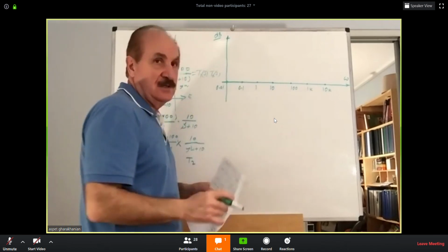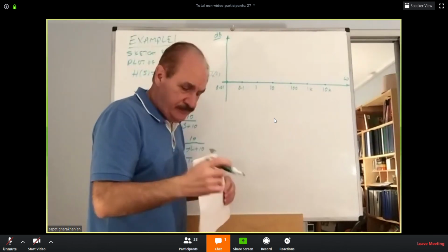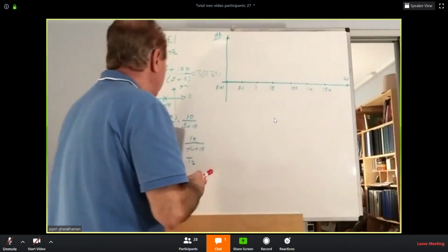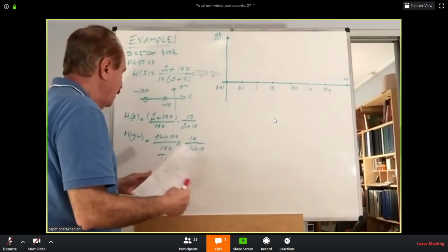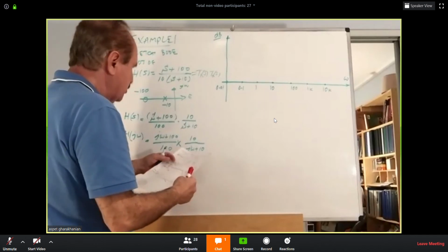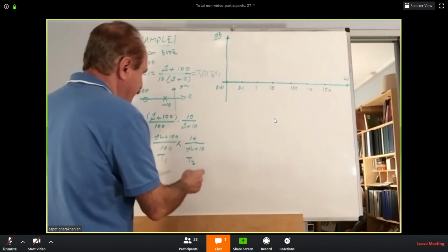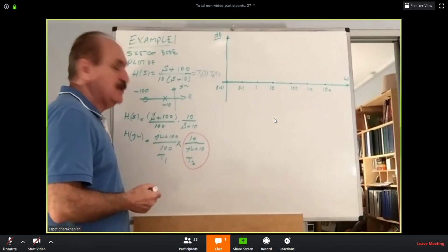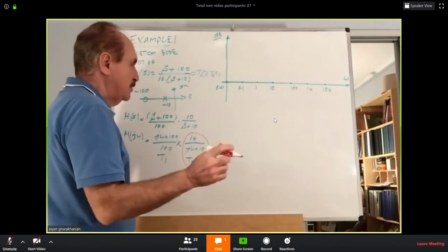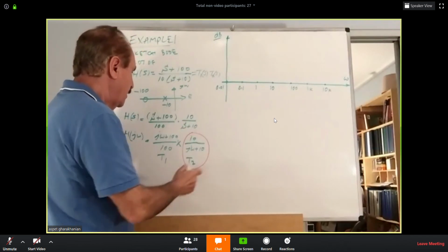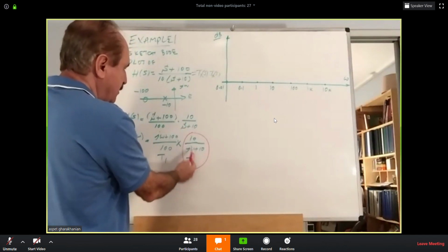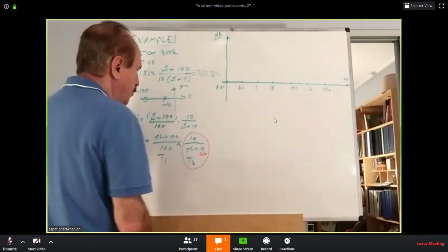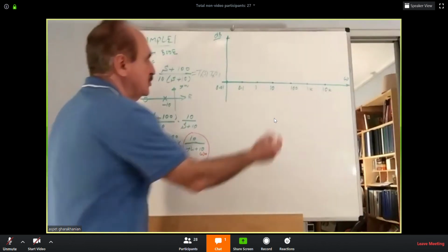Let's do the gain first, utilizing our standards. So remember what I said. Let us start with the pole, T2. Let's graph it systematically. I look at that, identify your omega O. Your omega O is 10, so go mark it.